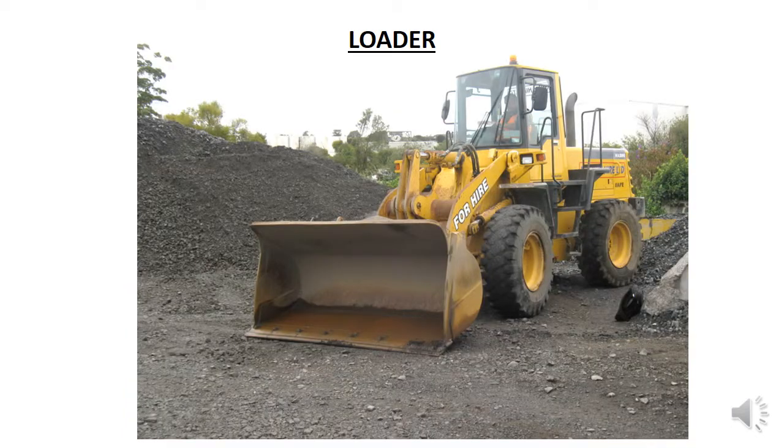Loaders are used to load loose materials onto trucks, or to transport loose materials, aggregates or tools short distances. In other words, they're like a motorized wheelbarrow. They are not designed for excavation of soil masses or for excavating below the ground. They are only able to pick up loose material from the ground. This material may be soil that has been loosened up by excavators or rock that has been ripped by bulldozers, and the loader usually loads this material onto trucks.